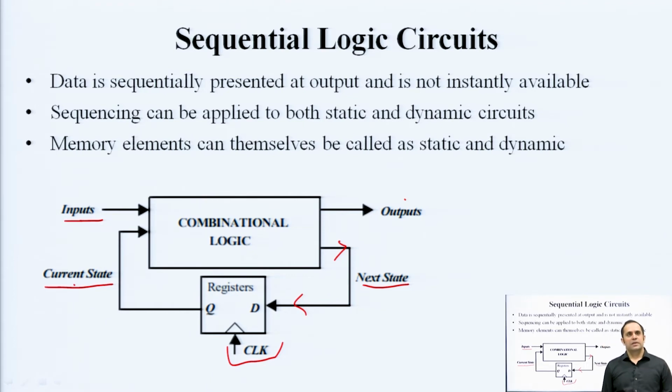The data in a combinational circuit is always there, it is always present at the input. In a sequential circuit it is generally presented sequentially, bit by bit, which is known as serial interfacing, and in some cases it is also presented in a parallel way, which is known as parallel interfacing. But the triggering is controlled. It is not that as soon as your input changes, the output toggles or changes. That is not the case. And depending upon the memory elements, if you can classify memory elements into different categories, that basically becomes the category of a sequential logic circuit.